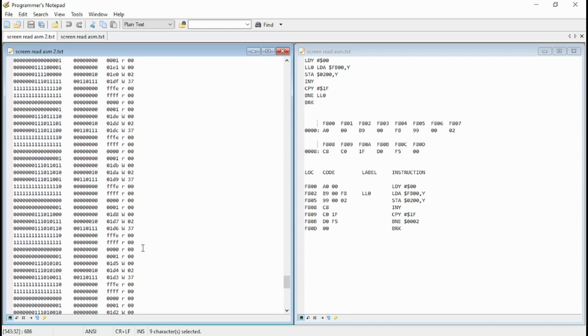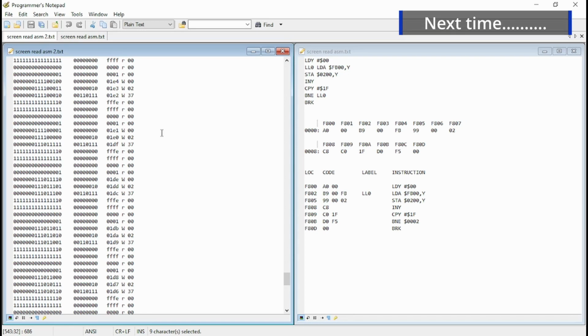We've managed in this episode to put together a CPU, put in some test code, and monitor that test code with a really useful way of doing it with an Arduino that's done it nice and slowly. It gives us plenty of time to have a look at the address lines, the data lines, and the read-write cycles, and compare that it's doing what it should be doing. We found out a few things about how opcodes are working, and a few things that the CPU does that are slightly odd and non-intuitive. So that's it for this episode. Next time we'll look at how we recreate the same system on the 6502 circuit in Verilog. So see you next time.